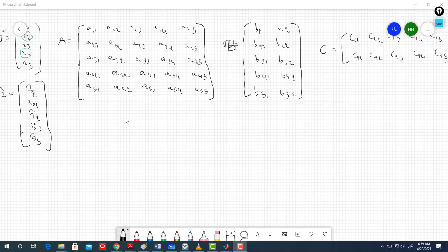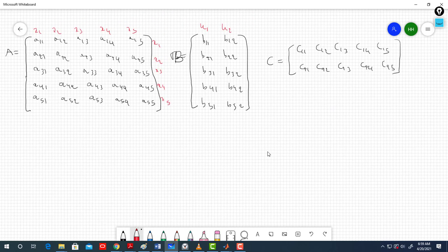So here you go, I write all the 5 states for the matrix A offline: x1, x2, x3, x4, and x5. Same x1, x2, x3, x4, and x5. So you have 5 states, and how many inputs do you have? u1 and u2. You can know that from looking at B. In this example, how many outputs do I have? In this particular example, just for the sake of demo, I also have 2 outputs, y1 and y2. From C, I know how many outputs I have.